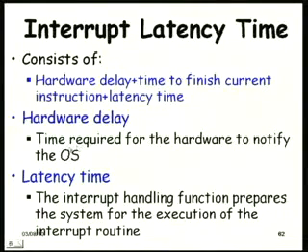So, the hardware delay is the time required for the hardware or the sensor to notify the processor. The latency time is when the interrupt handling function prepares the system for execution of the interrupt routine, basically saving the context and all those.